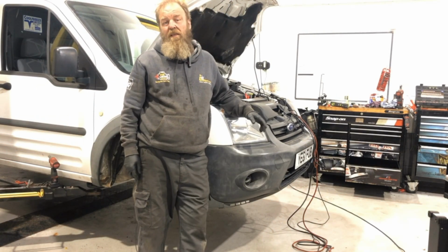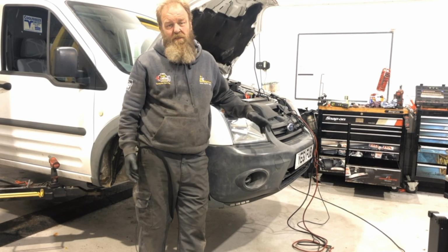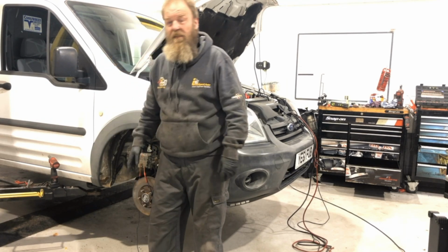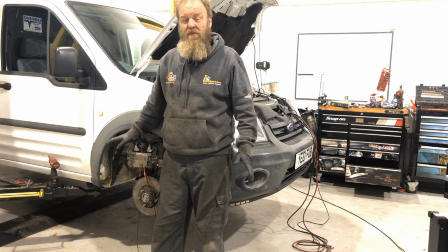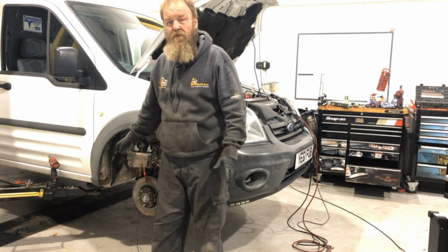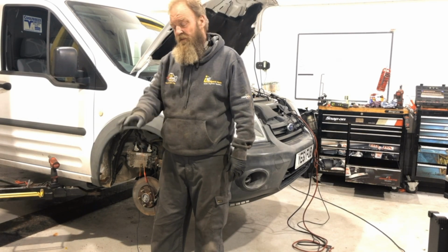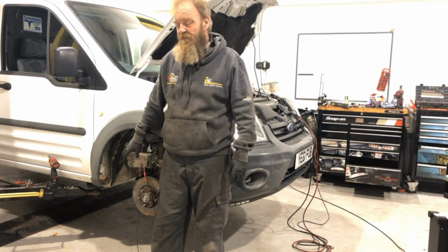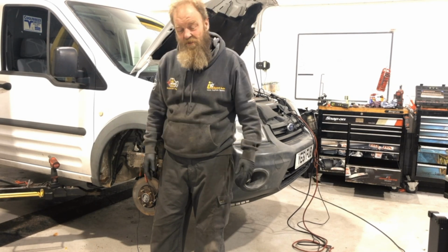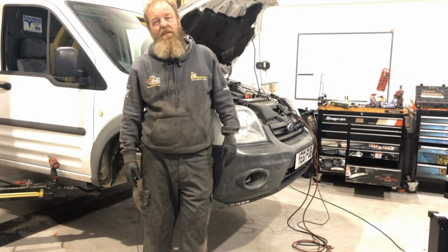The van went out, the guy used it for about a week, 10 days, and it broke down again, and it was recovered back in with the same crank sensor fault. So all I can assume is that the water is actually getting into the ECU. So this ECU is now going to get replaced with a used unit, which I'll code up to the vehicle, and hopefully that should be the end of it. The wheel arch liner will be refitted again to protect it. So maybe there'll be a second video for this one, maybe not, but there's a used ECU on order for it.